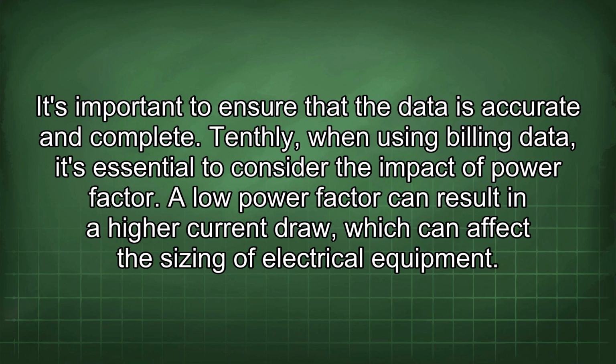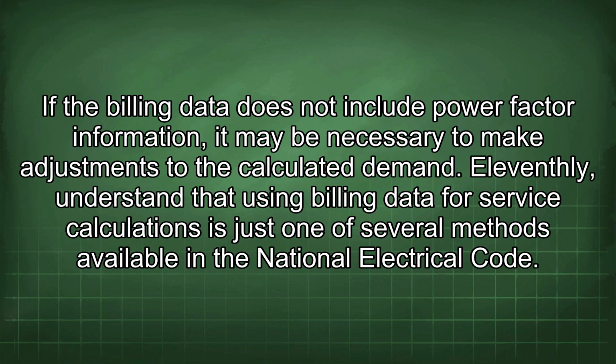Tenthly, when using billing data, it's essential to consider the impact of power factor. A low power factor can result in a higher current draw, which can affect the sizing of electrical equipment. If the billing data does not include power factor information, it may be necessary to make adjustments to the calculated demand. 11thly, understand that using billing data for service calculations is just one of several methods available in the National